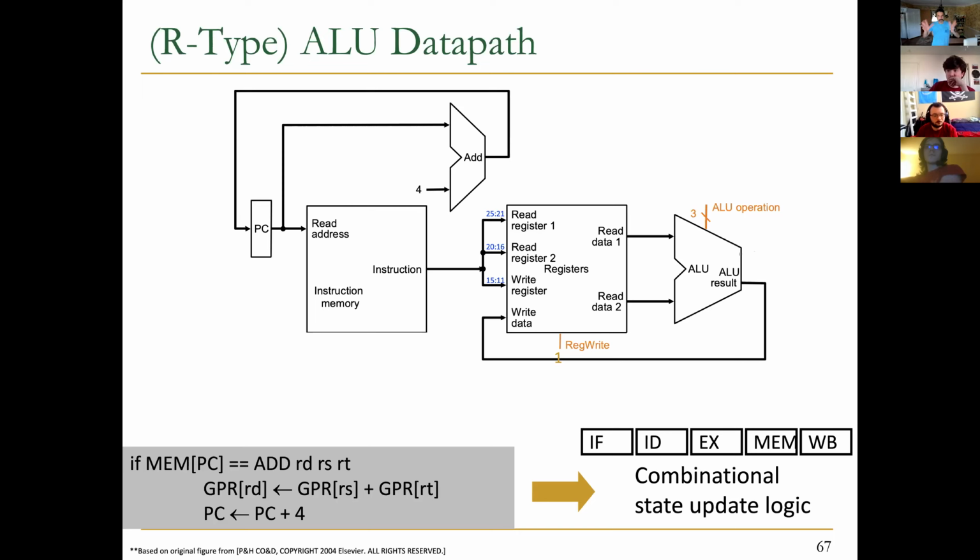So this is the data path. Each microarchitecture is constructed from data paths like the ones we just discussed. We had two data paths: one for incrementing the PC, and one for adding these two registers and sending back the result, writing to the register. So this is everything that we need in terms of data paths. There is nothing else that you need to do here.